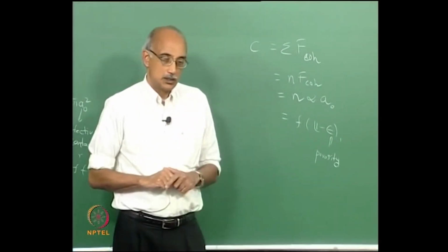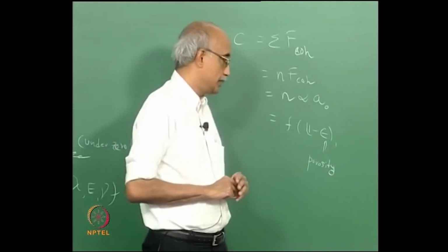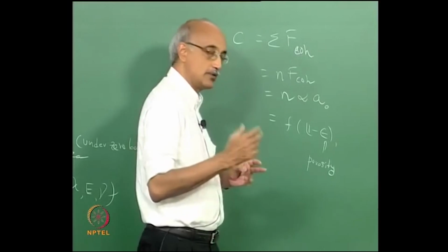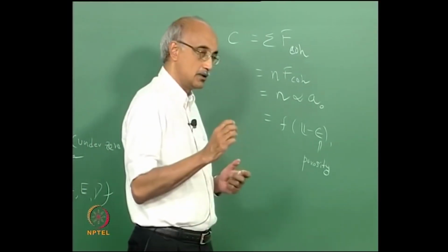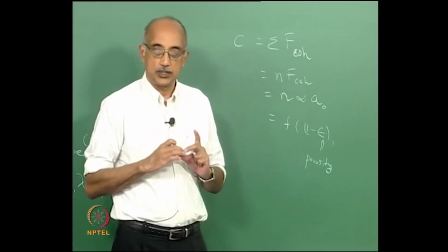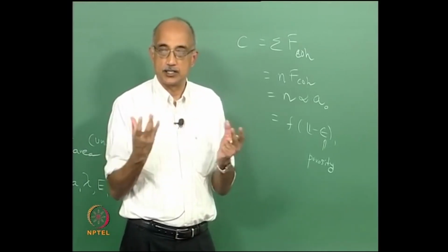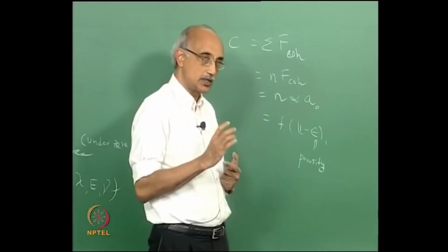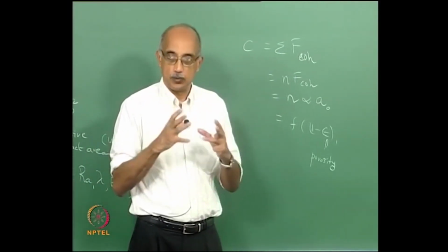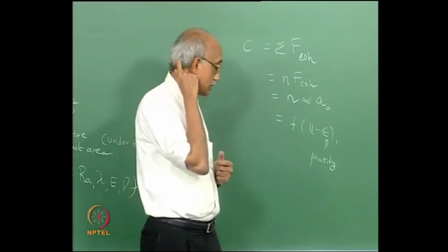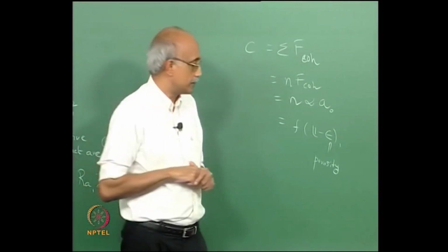In other words, the more porous the tablet, the less will be the cohesion between adjacent particles. So, if you formulate a tablet with high porosity, it is more likely to turn into a powder compared to one that has less porosity. So, in terms of manufacturing a tablet, one of the key considerations is always not to leave any open pores inside the tablet formulation to minimize any possibility of breakup.